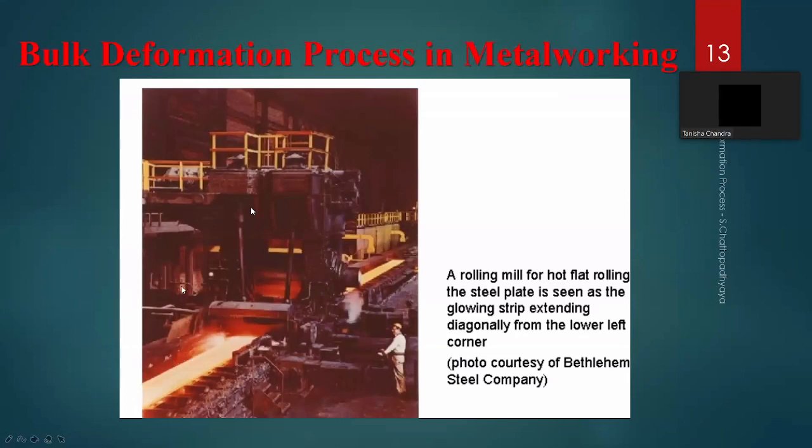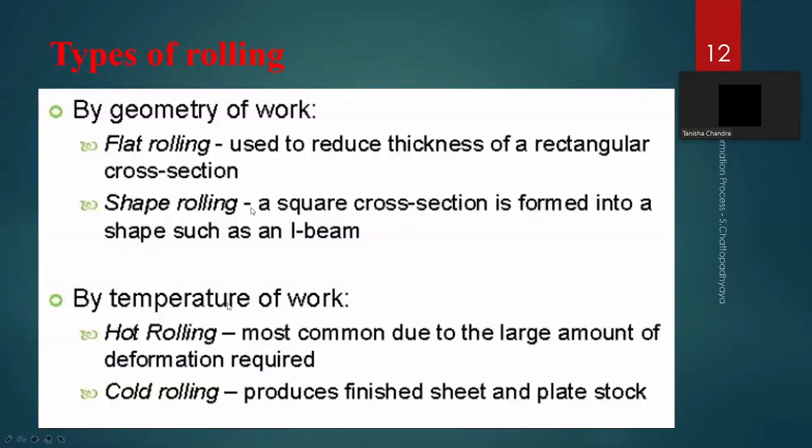So what you can see, these are rolls of mild steel plates. You see all those plates. You see all those bridges. Look at any bridge made of metal parts, not a concrete slab. They are all mild steel. You look at Howrah Bridge. It is made of mild steel. It has a lot of strength and easy manufacturability and easy weldability.